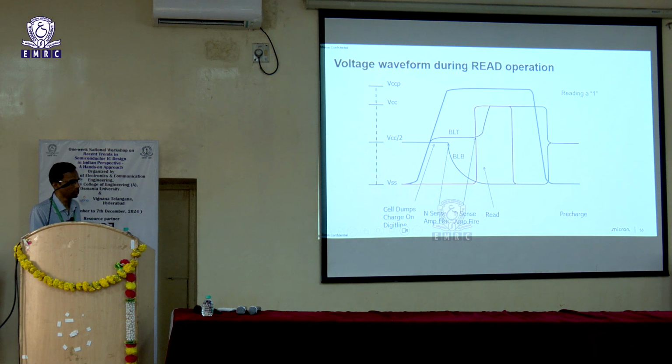So, the sense amplifier you saw is a cross coupled structure. You had NMOS cross coupled and a PMOS cross coupled. Here it is shown in a way wherein you enable the NMOS cross coupled first. The NMOS, which has a higher gate overdrive, pulls the other bit line low. So, this goes low and the other is almost tapered,